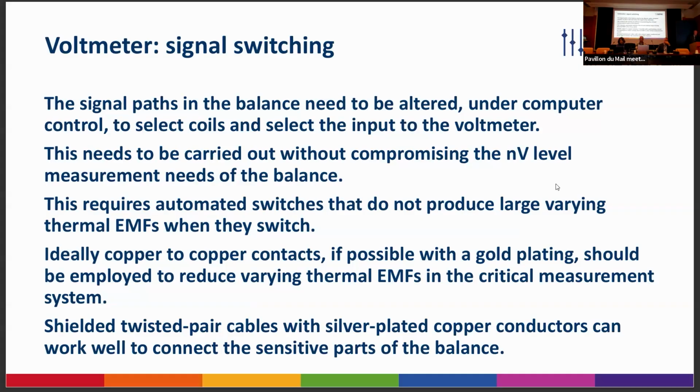The other thing that you need to do when you're configuring these machines is to effectively check. You have to be able to change the signal paths in the balance. And if you're trying to measure at nanovolt levels, you need the switches to work at that level as well. And it's surprising how few people sell switches that work at this level.